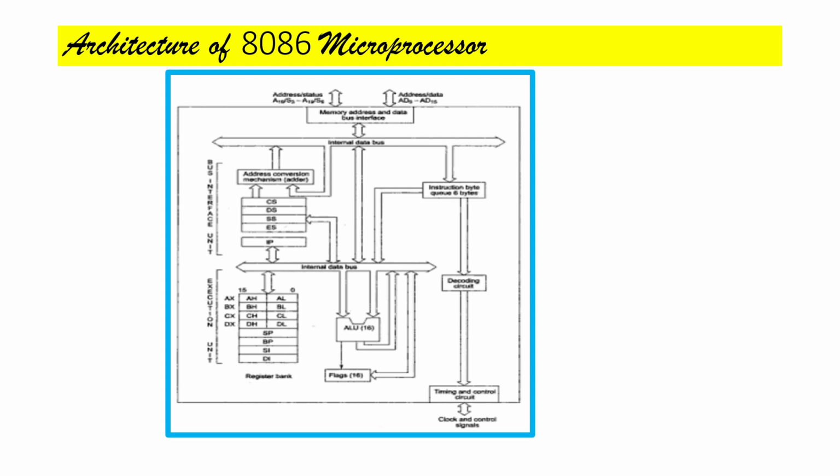There are three memory locations starting with 20,000H. The first data is stored there. In the second one, 20,001H, the second data is stored. I'm adding these two data and finally storing the result at 20,003H. So how is 20,000H generated? That's a combination of the segment registers: code segment, data segment, stack segment, extra segment. You can choose the code segment register value as 2000H and the IP value as 0000H.